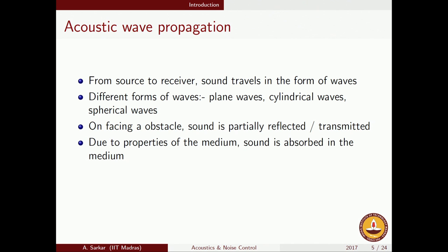Other than the fact that there is inherent viscosity in the fluid, there is also another important feature, that of heat conduction. What happens, as we will come to know, is that when the sound wave travels within a fluid medium, there are different zones having slightly different temperatures. It is not a very great difference in temperature which you could possibly measure with an ordinary thermometer, but nonetheless there are differences in temperature between different zones in which the sound transmission is taking place. For example, the compression and rarefaction zones will have different temperatures.